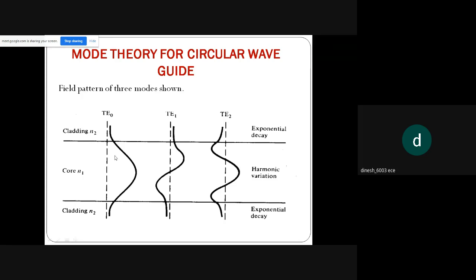field of propagation of your optical fiber signal is like this, where the field of optical fiber will be concentrated more towards the center of the core or the axis of the core. So at the axis of the core, the field pattern will be moving with a higher intensity. So this type we call as TE0. So 0 indicates that it doesn't cross the reference axis.